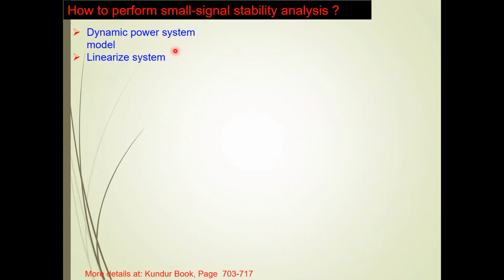Now, your generator is mainly a synchronous generator, right? The synchronous generator model equations, the differential equations that describe the dynamics of the synchronous generator, could be as high as a seventh order model, or it could be a sixth order model. So the generator state equations could be sixth order, and again a non-linear model. You have not only the first order equations but also the second order equations describing the system behavior.